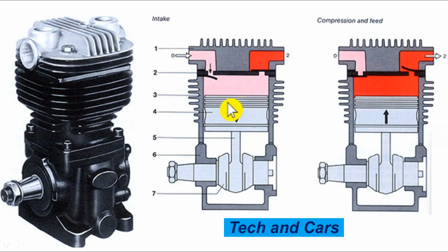Frequent short trips can also be to blame. We've said earlier, the compressor has to attain its operating temperature once in a while so that it can readily remove any moisture. Now, if the air system never gets hot enough to evaporate moisture effectively, that can also cause a large amount of moisture to mix with the compressed air. And the other thing is, obviously, where you use it. If it is a very humid operating environment, that can also be a cause. Operating in a highly humid area will naturally put more water into the system, stressing the air dryer. So these are some of the things that can cause excessive moisture inside the system as well.